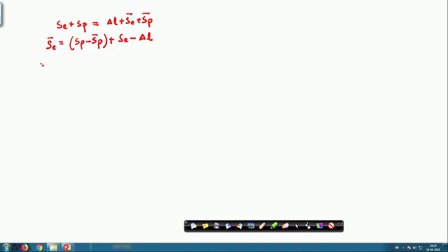So, that means the pile settlement is always recoverable. Okay. So, that means the total plastic settlement that you are getting is due to the soil only, because we are assuming that the pile will never be in the plastic zone.